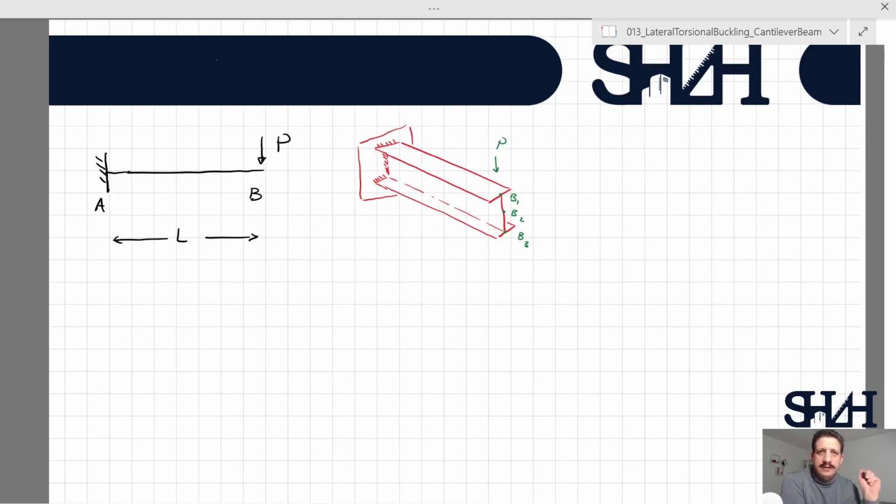Now, the idea of lateral torsional buckling is that when the load cannot go further in its plane, it starts to move laterally. So writing the total potential energy equation starts from the moment that the beam starts to move laterally. As a result, the energy which is lost or stored inside the element is not considered until it starts to buckle laterally.